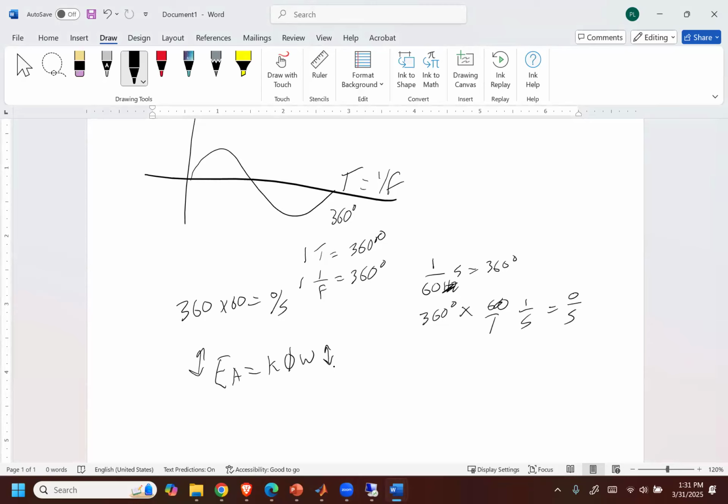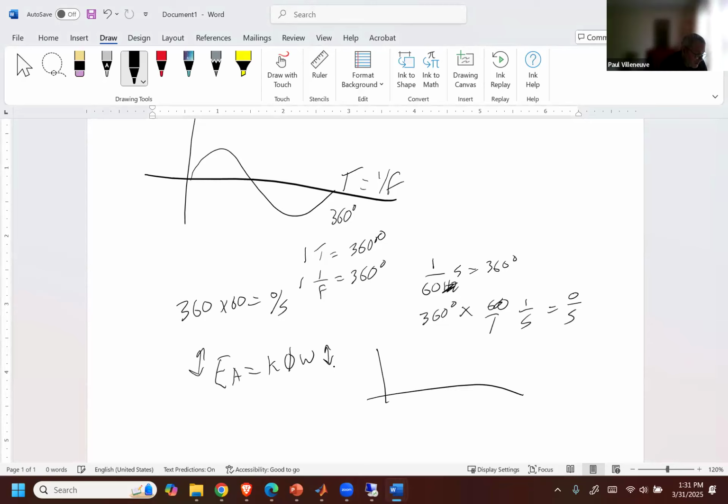So this is going to give me a curve. As I change my speed, my terminal voltage is going to start low and then ramp up. Regardless of adjusting the field current, I'll get some nominal value of field current, and that voltage is going to increase or decrease linearly because omega is increasing linearly.